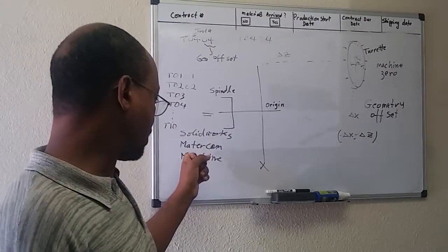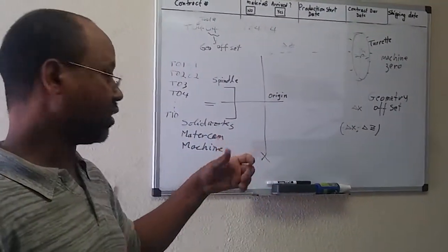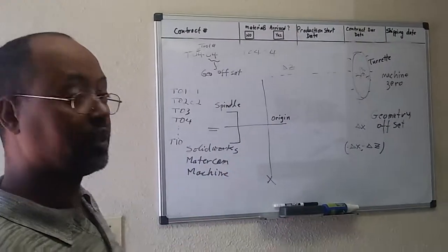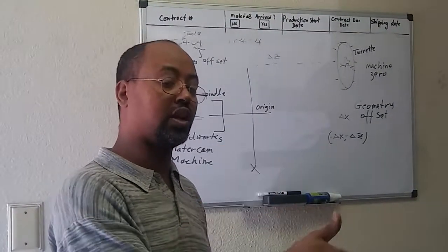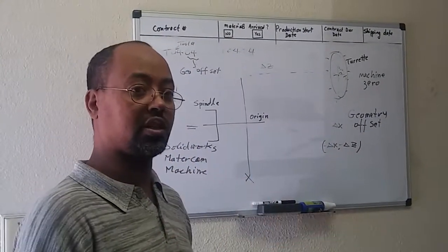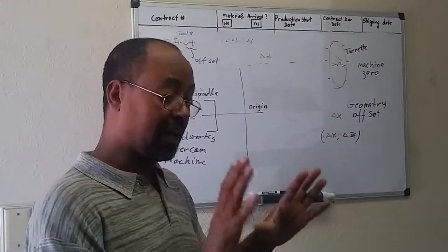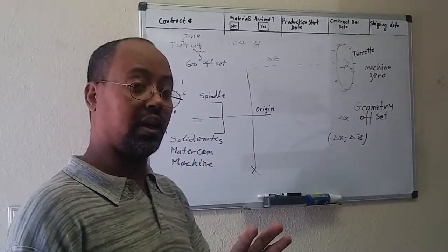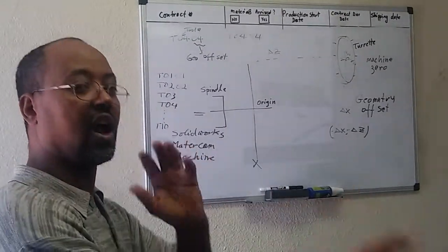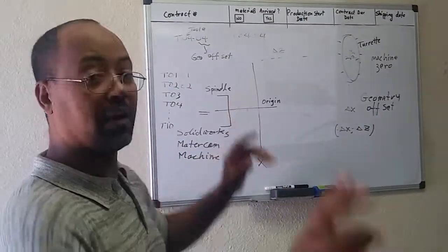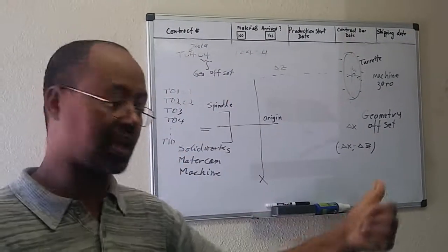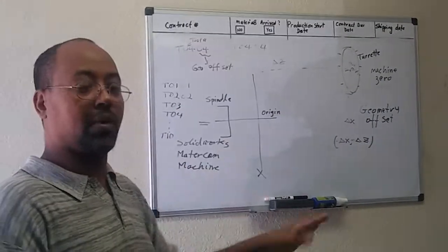You're saying for Mastercam and SolidWorks, the origin is like a virtual thing. You could see it, it's right there. Once you turn on your grids, you know where they're at, right? Yes. And depending on which plane you draw on, if you draw something in SolidWorks on the top plane and open it in Mastercam, it will always match. But if you drew it in SolidWorks on a different plane, then you have to move the part around or rotate it. But now we already know we draw everything on the top plane and then open it using Mastercam. Now they both have the same origin. No problem, they match, right?